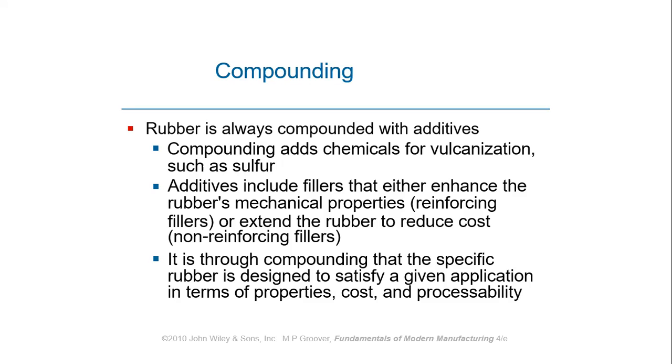Okay, color can be a non-reinforcing filler, and reinforcing filler would be like, if you look at the rubbers that have a small reinforcement, various kinds of natural fibers or sometimes synthetic fibers like nylon are used to enhance the mechanical property of the rubber. And that's the purpose of compounding, to add additives to the rubber to enhance the mechanical, physical, or processability properties of the rubber.